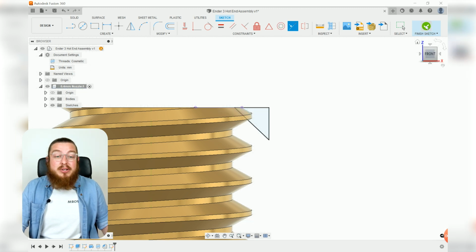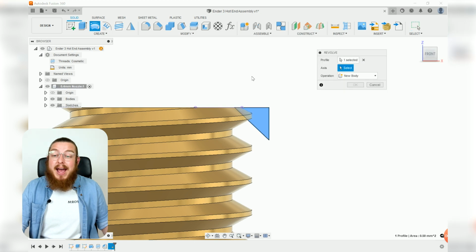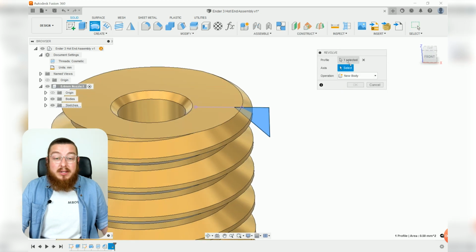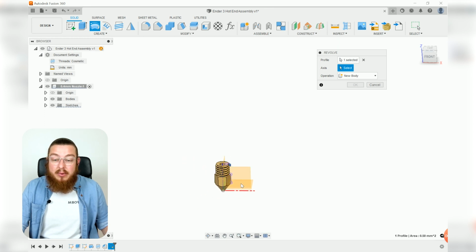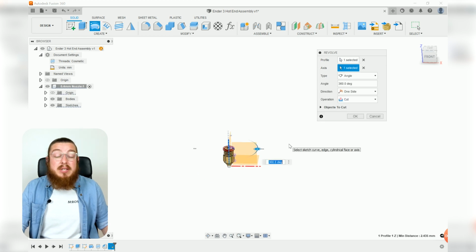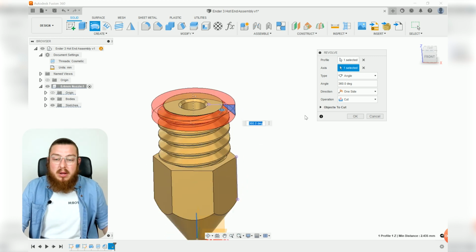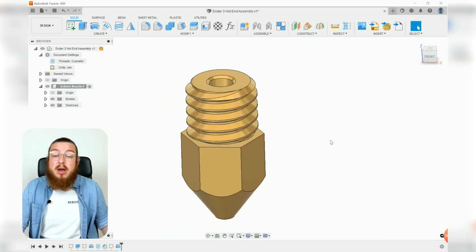And as you can imagine, we're going to be finishing this sketch and then adding a revolution cut about the axis. And this axis is going to be a little hard to click. So we can either zoom all the way out and select that, or you can just rotate your piece to the underside so you can kind of see through that hole on the bottom. But that's looking great, so we can just hit OK.